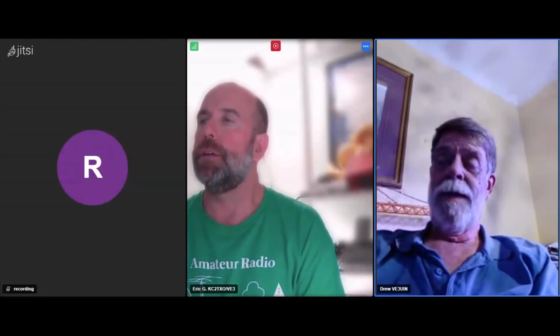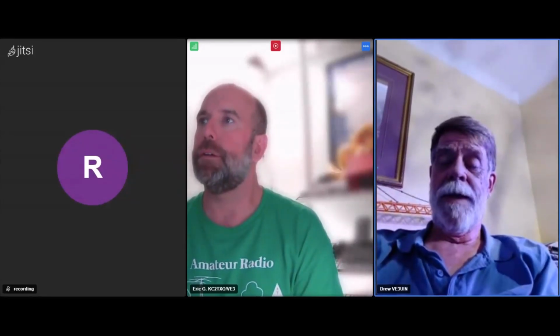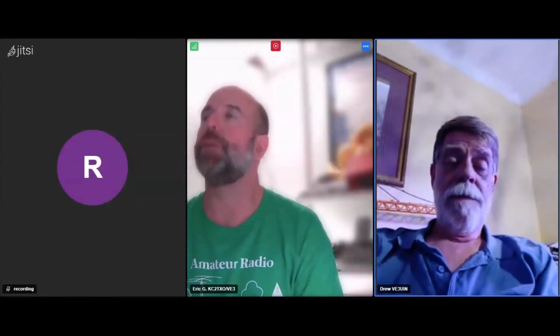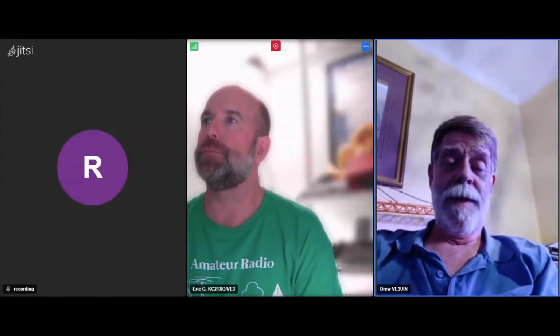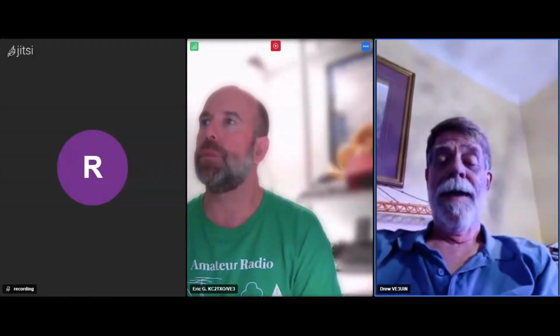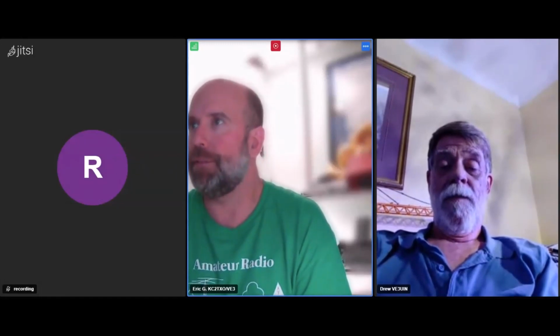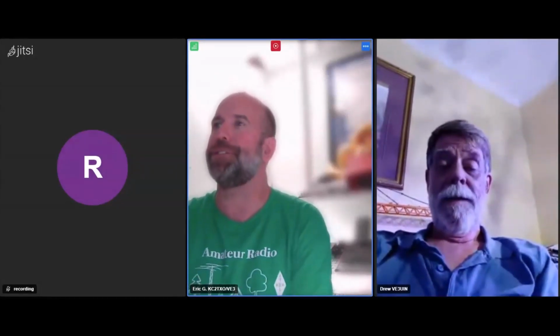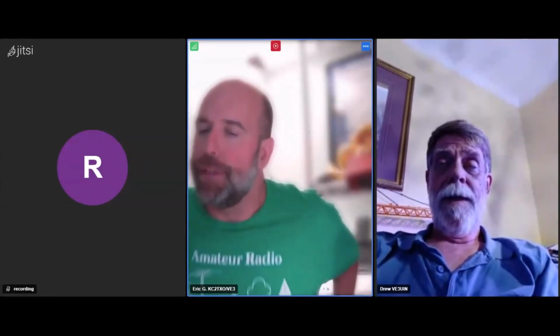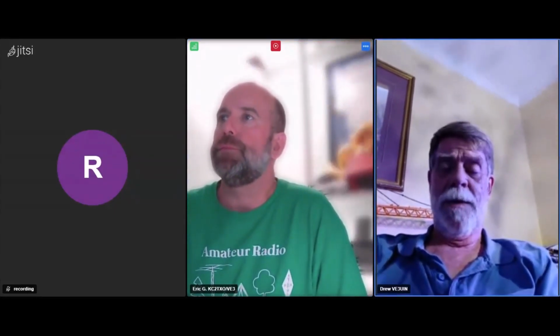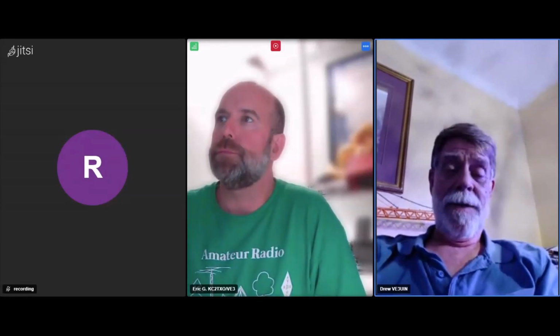That's basically what the calibration stuff is for the NanoVNA. You get a 50 ohm resistor and you put it across the end of it, and it tells you, yes, this is 1-to-1. If it's something else, then you've got a problem. Your device is suspect. And I like the NanoVNA because it'll sweep from 0 to about 30 MHz, and you can see where your antenna's working and where it's not.